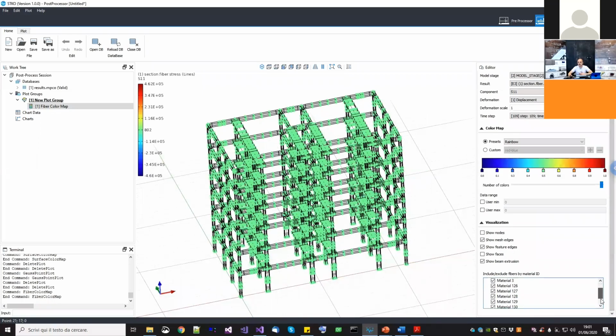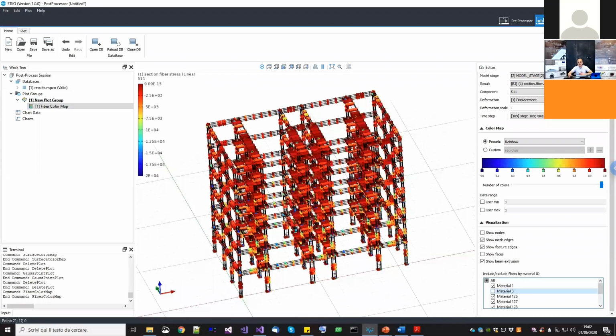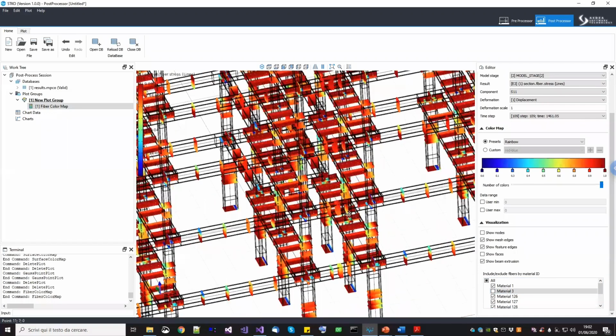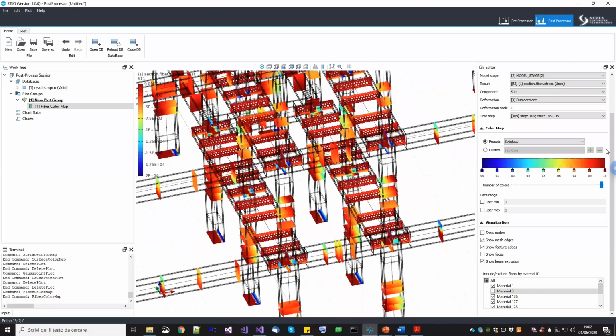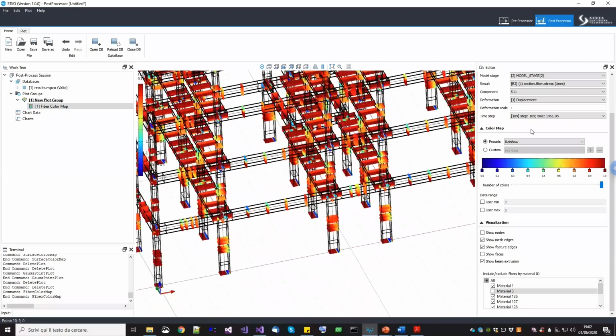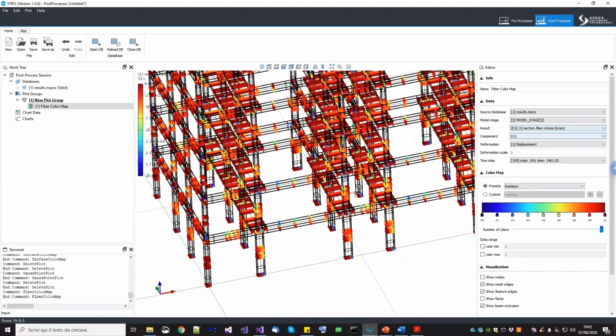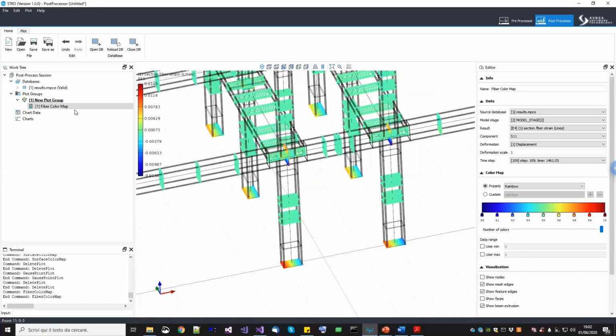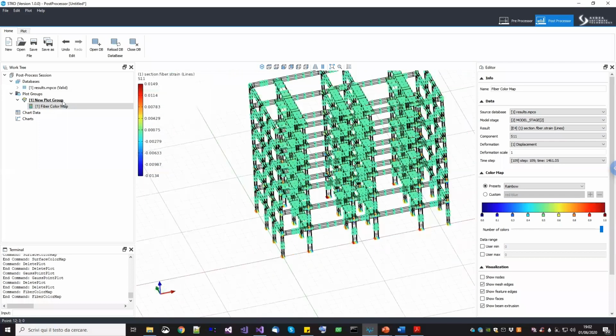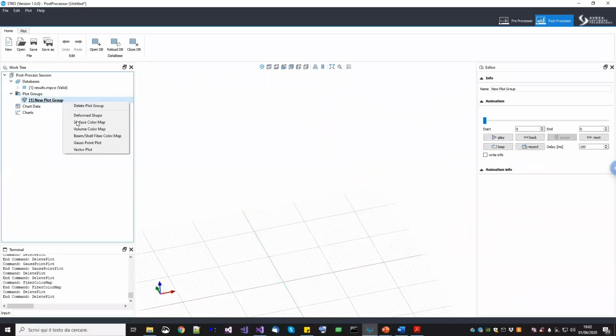So here you have many material models. Why do you have so many? Because you know that you only have one concrete, because all the others are automatically created concrete, okay? So for example, this one will be the steel. I can remove it. So all of them are concrete. And so you can visualize the stresses in every component, stresses or strain. Probably it's easier to visualize the strain to understand what's going on in terms of plastic hinges, okay?